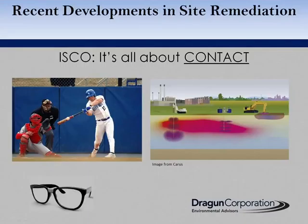A good thing to take note of here is that if ISCO is determined to be the most feasible remediation option for your site, you can greatly increase your probability of success of the ISCO program by conducting a detailed pilot study or bench scale testing of an injection program to determine the best parameters for your specific site. From this, you can determine the optimal injection pressures, oxidant mixture, radius of influence, natural oxidant demand of the soil, among many other things. From our experience, the most common finding from our pilot studies is that low pressure injections using proper lateral injection tooling is usually required to meet remediation goals.